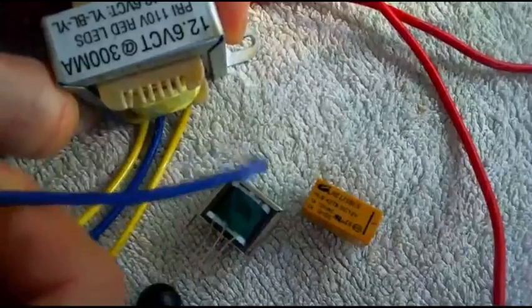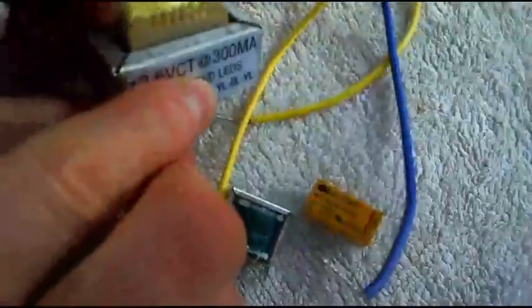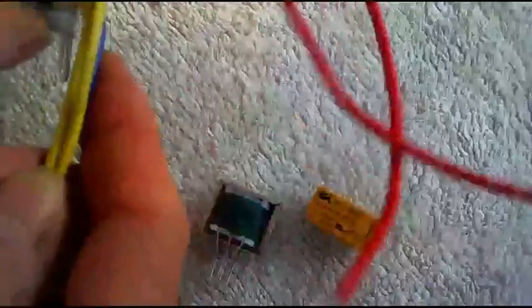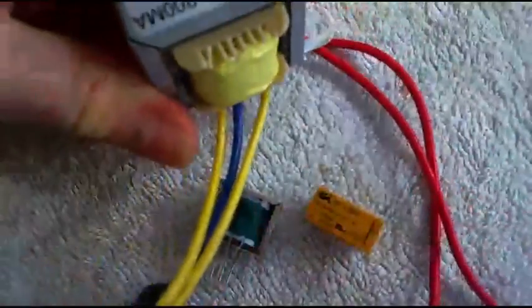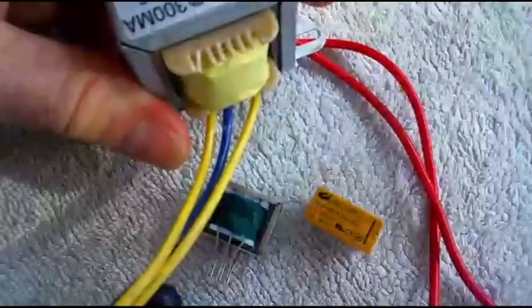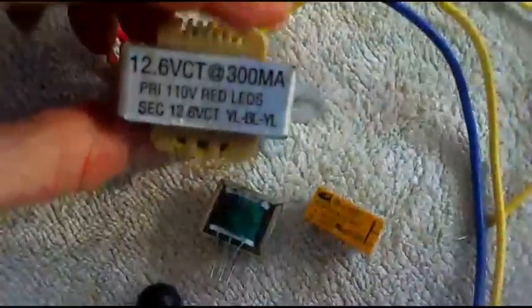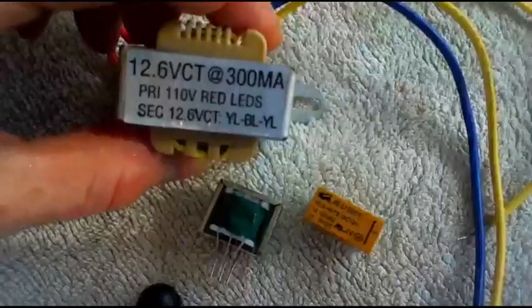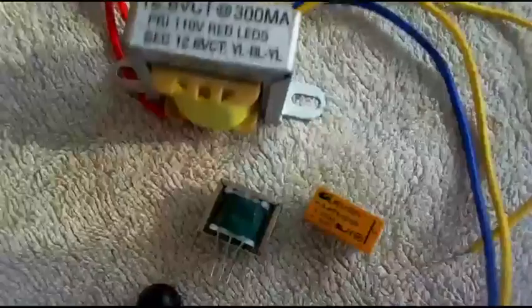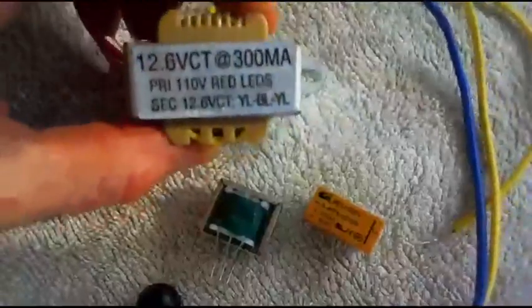And because it has a center tap, that's what the CT means in our labeling, on the secondary side we have easy access to all the windings or half of them. In either case, as we go on in this video, we're going to measure the actual inductance L of the primary side of this, which we would expect to probably be fairly large.